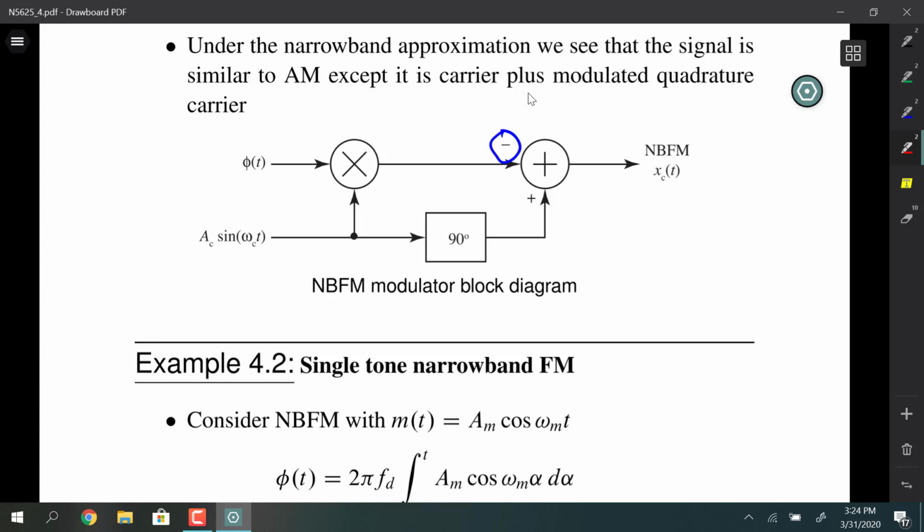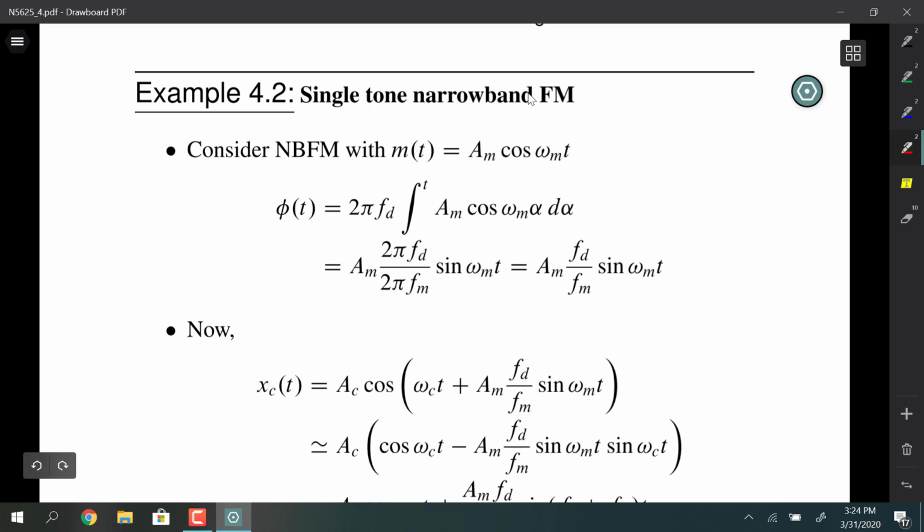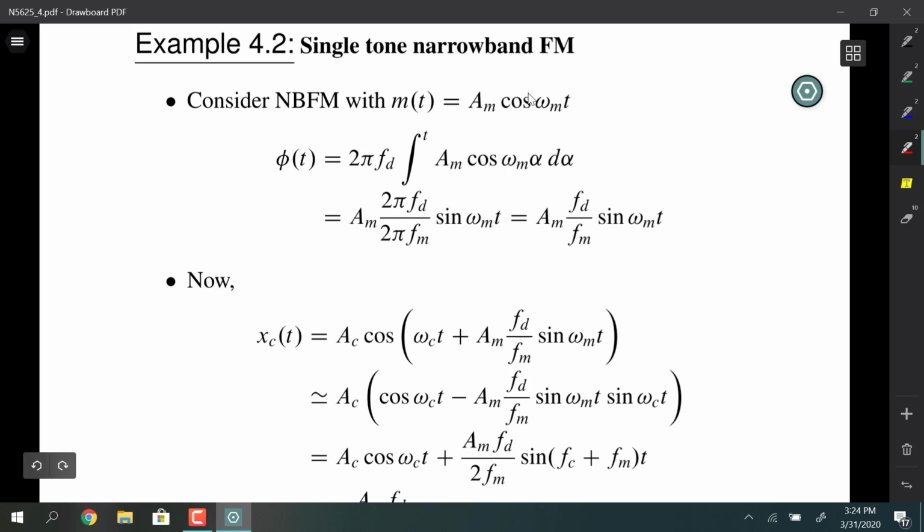It's a constant envelope. So here's an example of just carrying it through with narrowband tone modulation where the message is a cosine. You can take the FM version of the angle modulation. So the message is Am cosine omega m t. We have to integrate that to get the phase deviation, and that becomes a sine, and then there's some scale factors that get thrown on there.